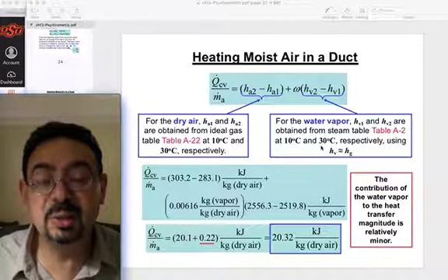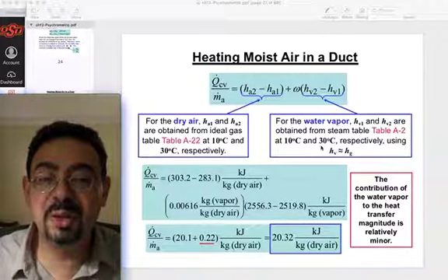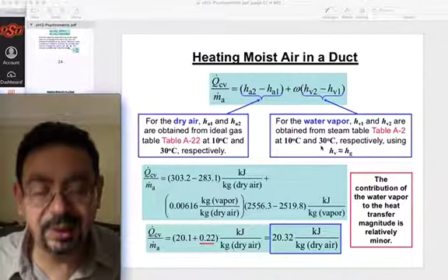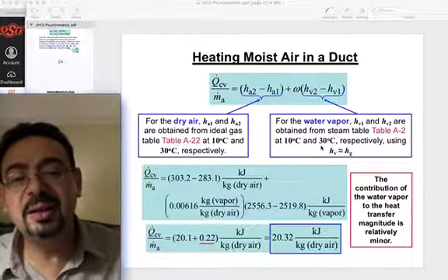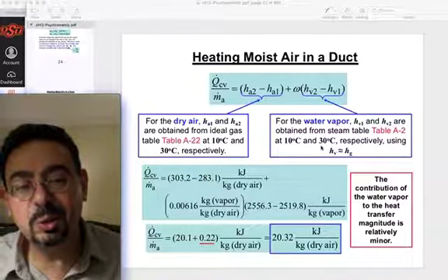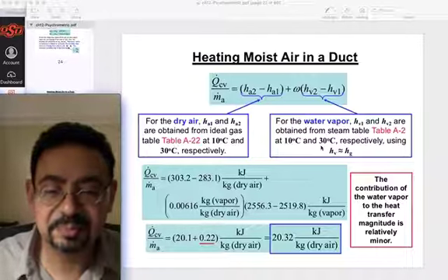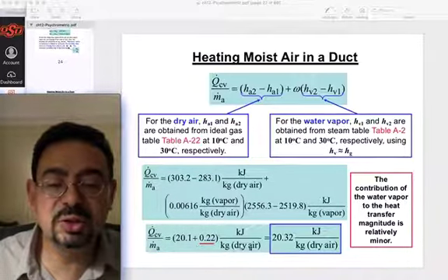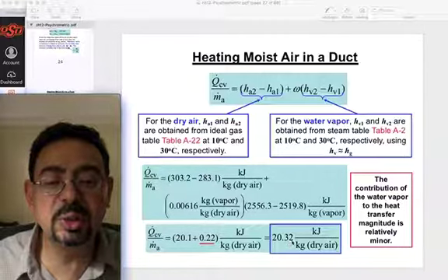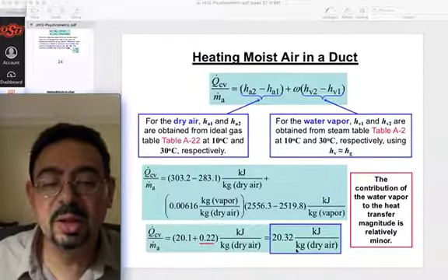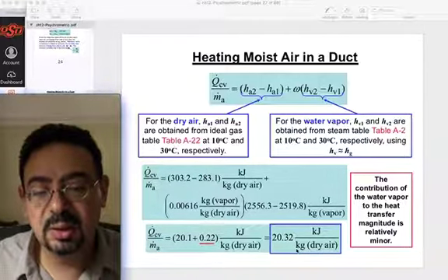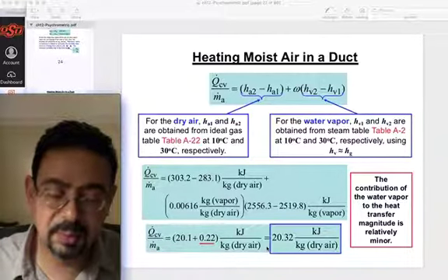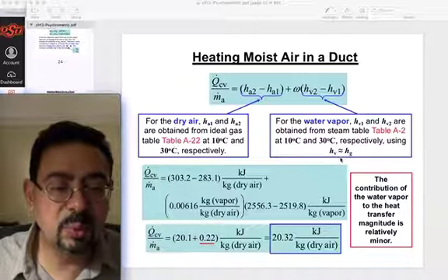Because my humidity was not 100%, my humidity was 80%, and we will know shortly that when we even heat the air, the humidity ratio will drop and drop and drop, right? But anyway, you can see that the difference wouldn't change that much. It would be, rather than 20.32, what, 20.35, 37, right? So you know what's 0.05 between friends. So the book will use this approximation.